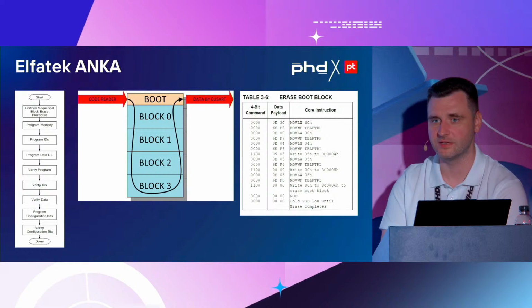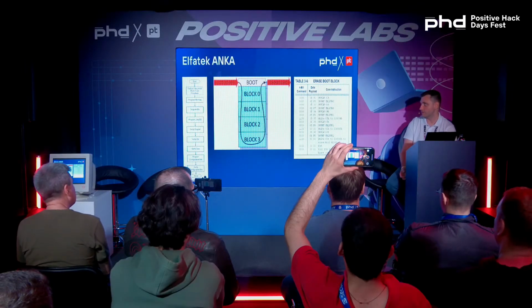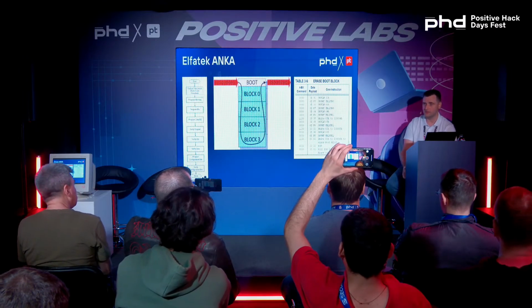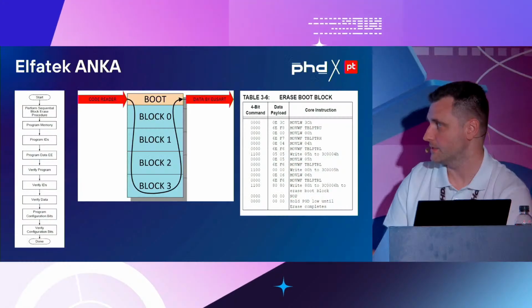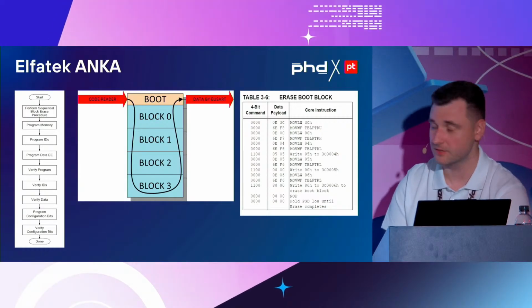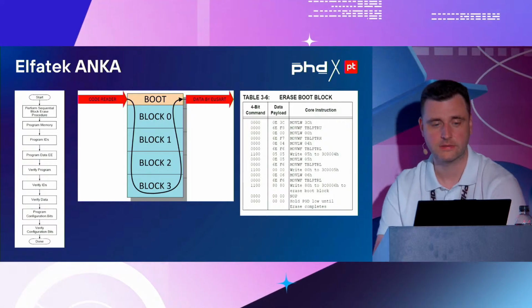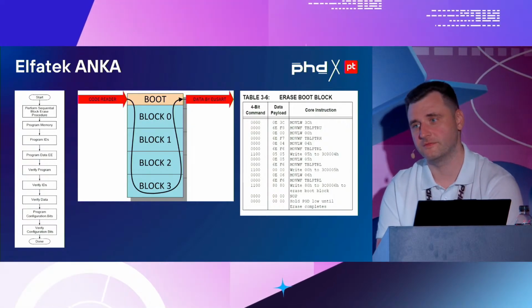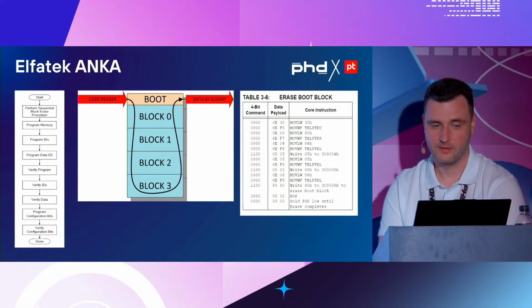So it looks quite easy, and in essence, this is something that disappoints me about the research. You know what has to be done, you have to do that routine, and you make the same mistakes that you didn't want to. So PICkit cannot erase BootBlock. It can erase the full block. We looked at the datasheet, and the datasheet says what commands have to be sent in order to erase BootBlock.